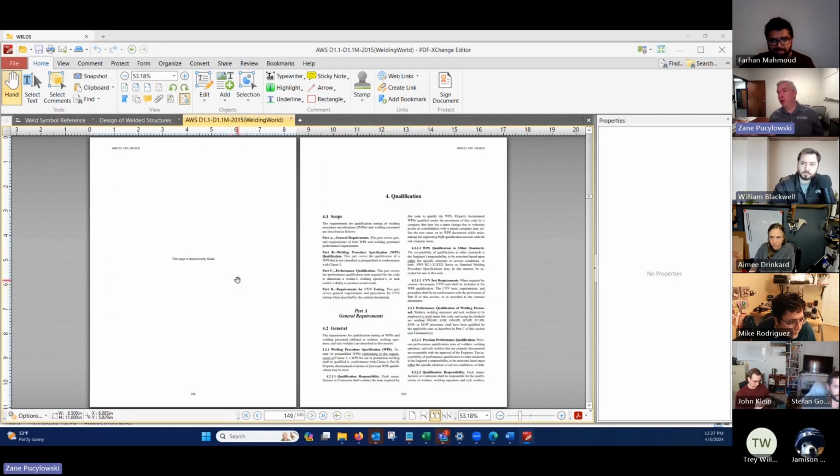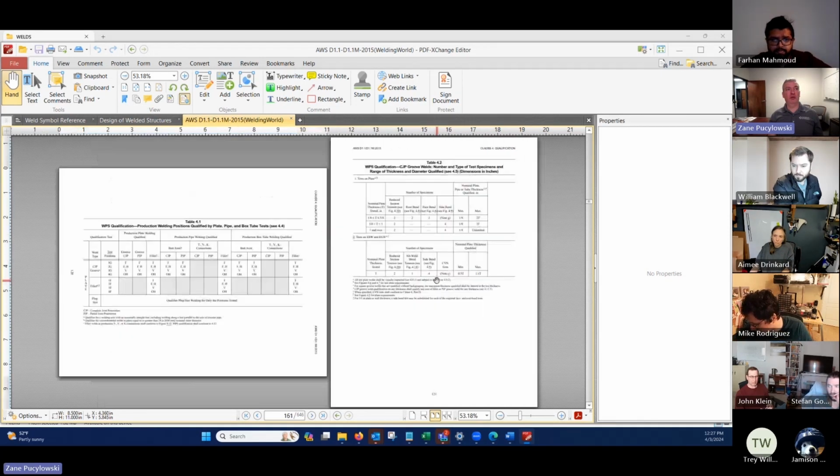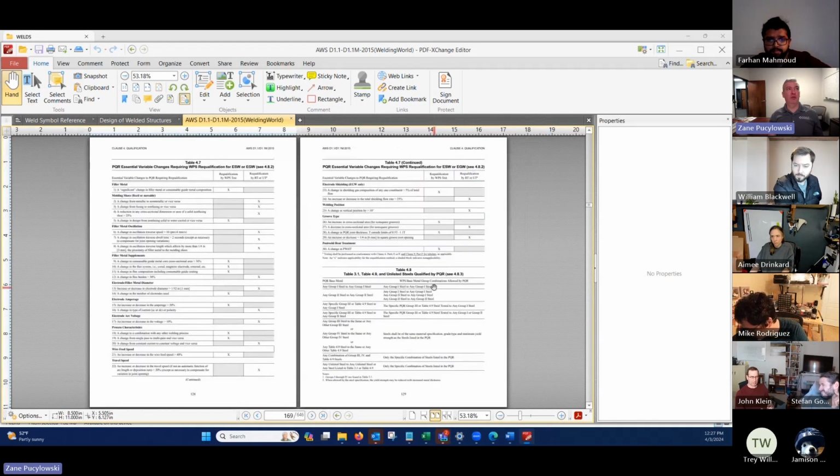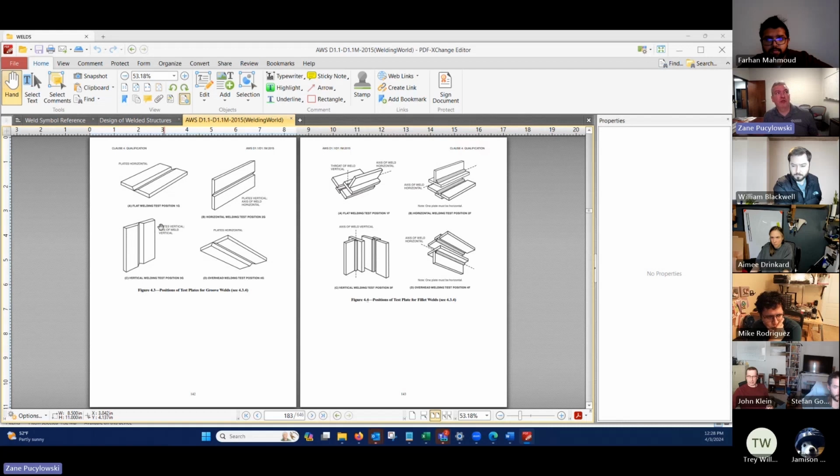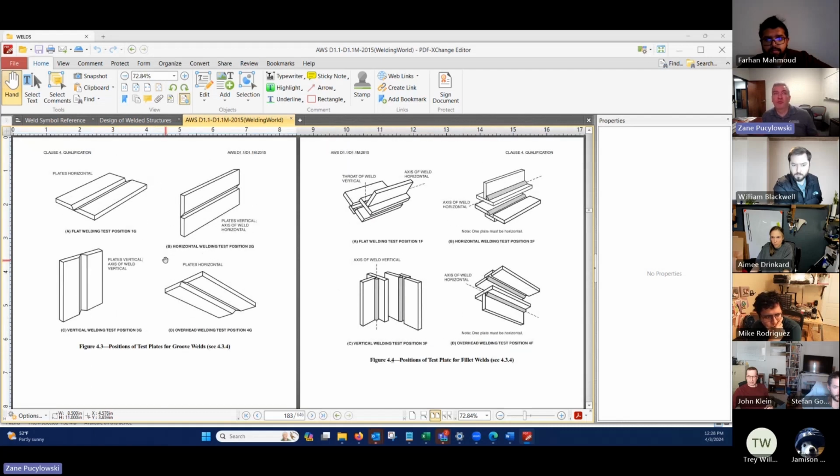All right. Now that we have a good joint, and I'm going to go a little long. Now that we have a good joint, we have to make sure the welder can do it. That's chapter 4. So the welder themselves has to prove they can make good weld material. And what you'll do is you'll have them weld different things. So this was what we were talking about a minute ago in positions. This is flat. This is sitting on the table. It's very easy. This is overhead. It's above your head. It's a pain. You're dripping weld metal on your back.